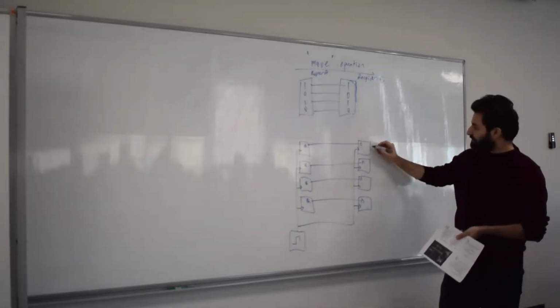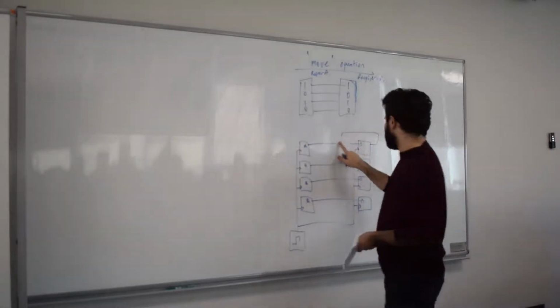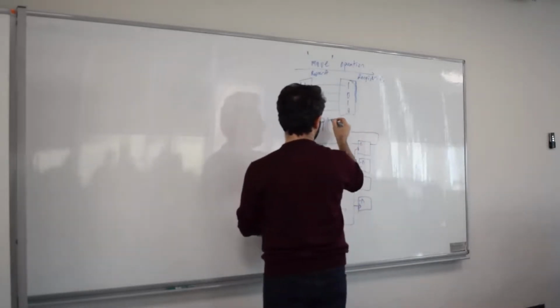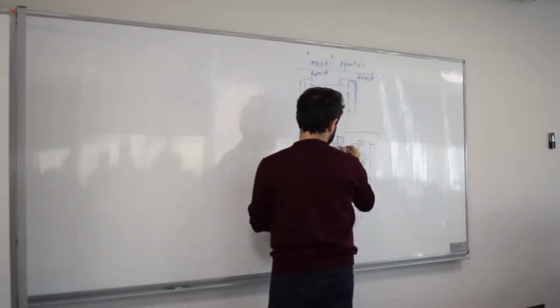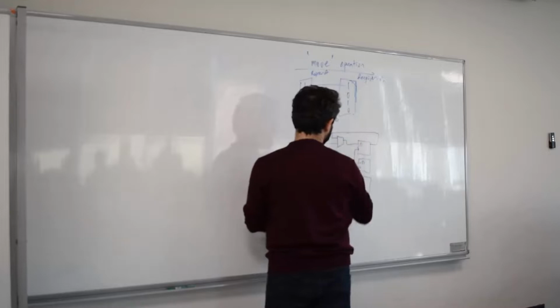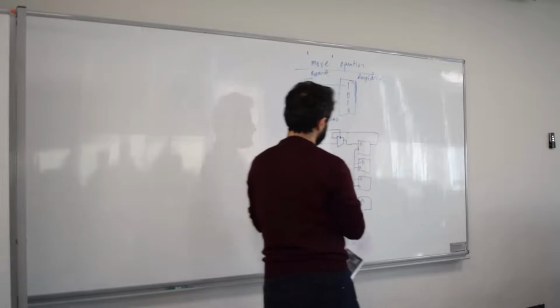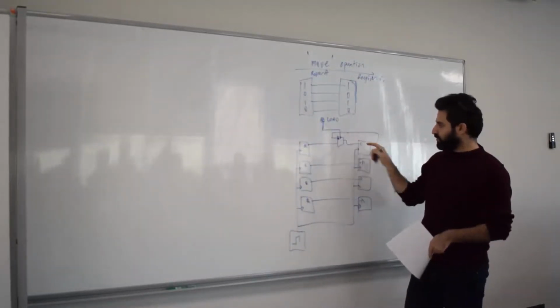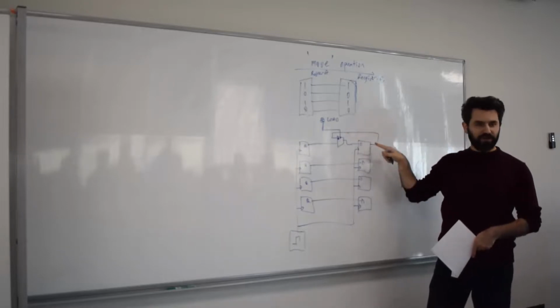So therefore, you have to carry this output information and put it back to D, if you're not loading it, right? So there has to be some load control coming in with a mux. So I'm going to connect this, and the mux select would be connected to the load information. If load is 0, I'm going to copy whatever I'm storing in the D flip-flop again back to D flip-flop. It's kind of a circle.